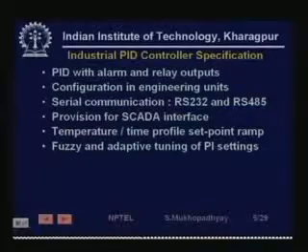Similarly, processes keep changing because of their characteristics. Furnaces, fire lining of bricks degenerate, heat transfer coefficients change, depositions. Typically in heat exchangers, heat transfer coefficients tend to change because of depositions. For example, let us say there is a plant in the Middle East where people make drinking water by using seawater. That is called a desalination process, and it is a very energy intensive process, and the heat transfer coefficient is very important.